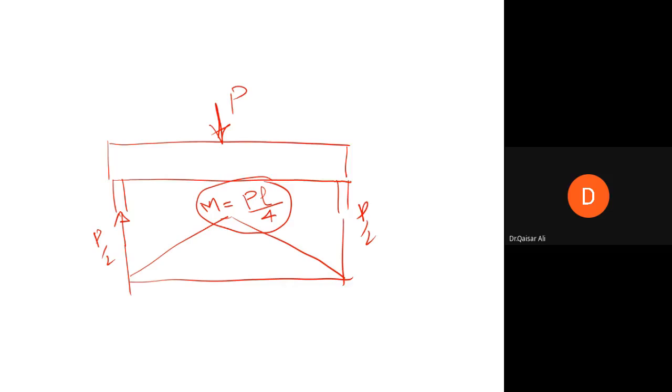This bending moment is being produced by what? By load. And this bending moment will depend on a situation because load is not in our control. A particular situation will create this load. A particular situation will demand that this load should be equal to this much P. So the demand will be created by a particular situation and it is not in our control. This is demand equal to PL by 4. L is the length of the beam and P is the applied load on the beam. So with the increase in length of the beam and increase in P, M will increase.